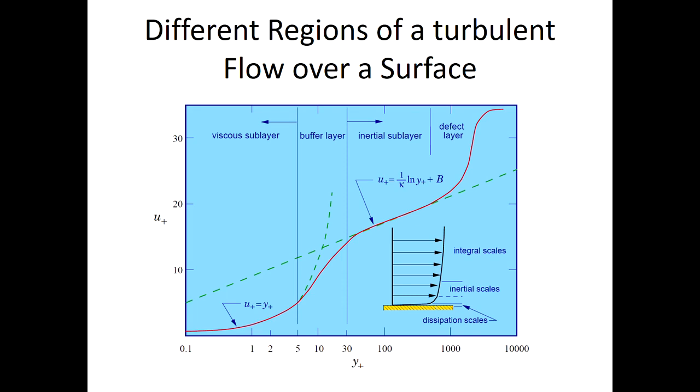Now this is the same velocity profile as shown in this curve, except I have made this distance equal to the logarithm of a quantity called y plus, which we will define later. This is the actual u velocity non-dimensionalized by some quantity to make it u plus. Again, we will show you how you non-dimensionalize it. Whenever you non-dimensionalize it, you get a universal curve like this. That's the power of non-dimensionalization. That's why we deal with the Reynolds number, Mach number. We want to keep everything non-dimensional if at all possible.